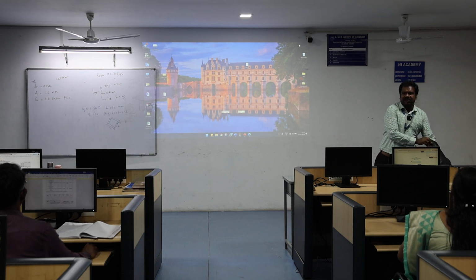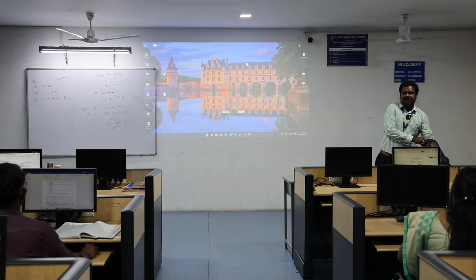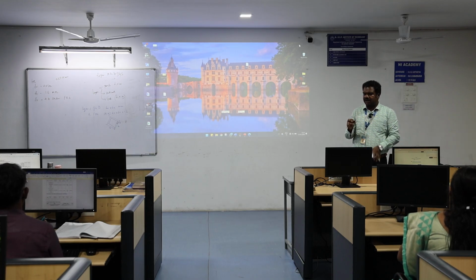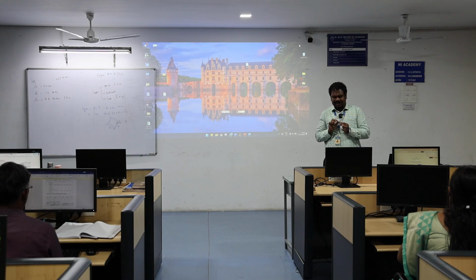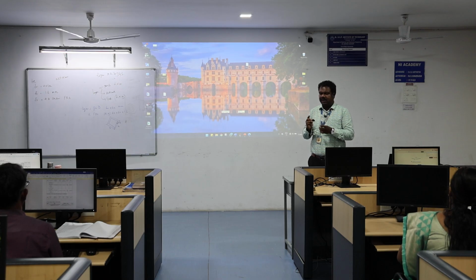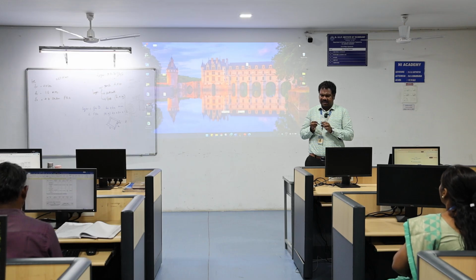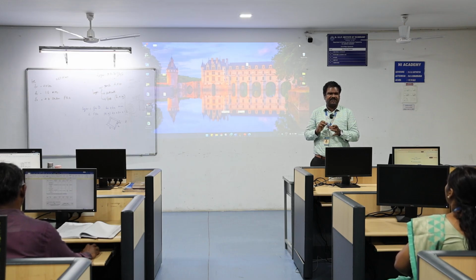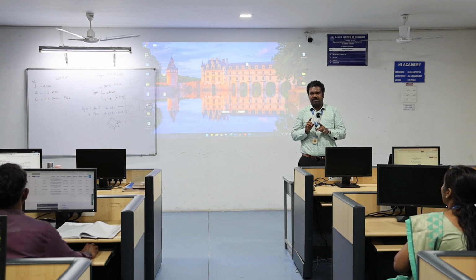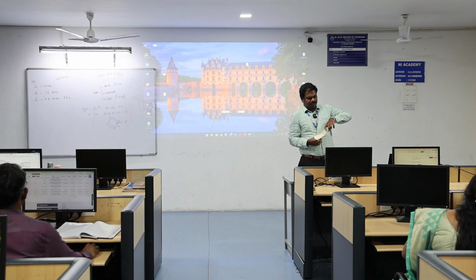That is a miniature type of antenna. Miniature antenna means the size is 10 centimeter by 10 centimeter. The structure is almost like a paper size patch. This is made of Kapton material, which is one of the rare materials. So this antenna is fabricated on Kapton. The patch and a defective ground plane structure are used. This is a miniature antenna, a fractal type of antenna. The same antenna is used for a different structure.